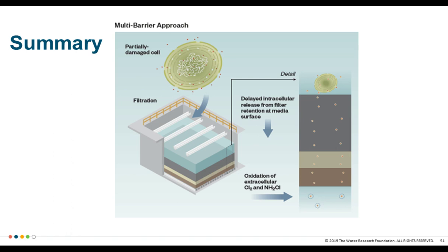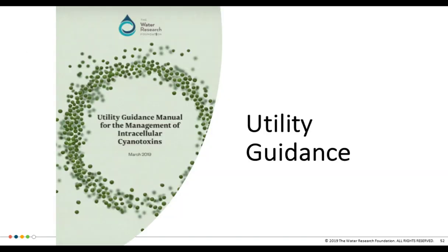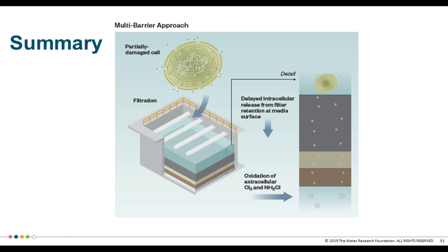If they are retained on a filter and just able to release cyanotoxins over time, it can present an issue where you would then want to look into perhaps applying a post-filter oxidant like chlorine, for example, ozone, where you know it will take care of cyanotoxins that have been released. And it may also make you consider, say, backwashing more frequently when you have a toxic cyanobacteria bloom. So it can impact how you think about those.